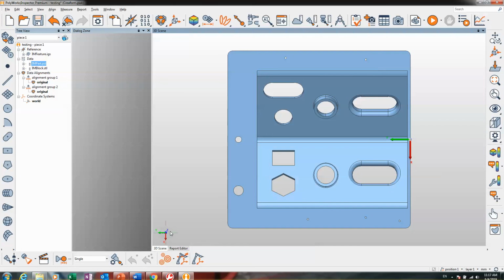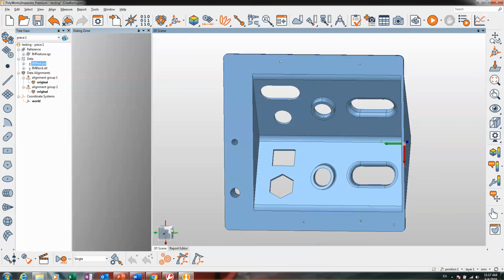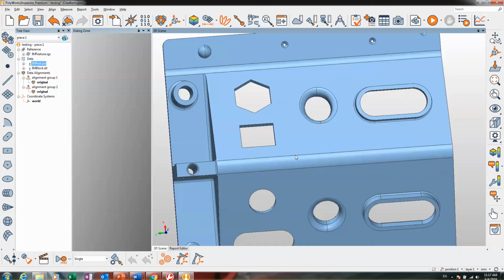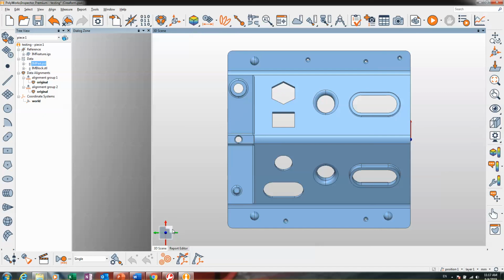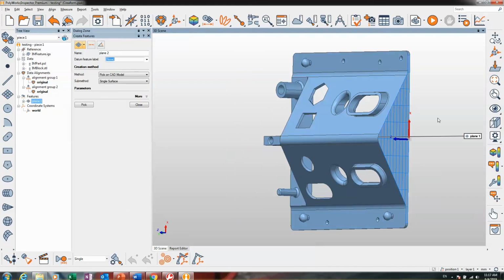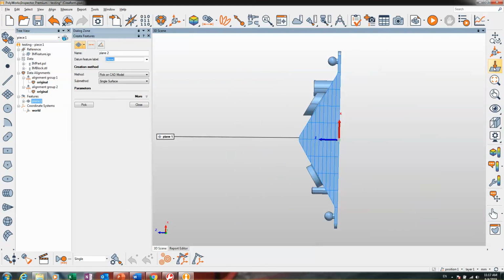You can also move the part by what we call the ISO view, like this. If you want the top view, this view is a Z plus. You just click on the surface. This view is perpendicular to the screen. Next icon is a normal view. Suppose when I create any plane here, and then I click here, it is the top view of the plane.